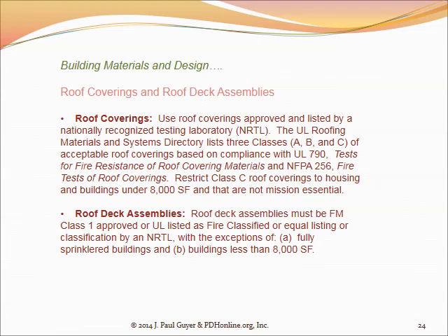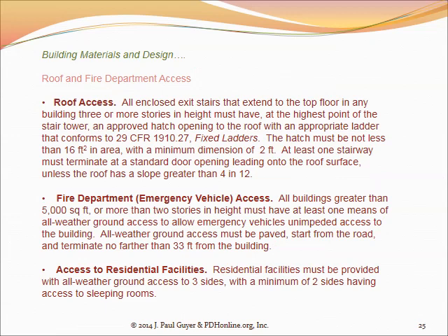Okay, another concept that is important as far as the roof is concerned, and really for the whole building, is accessibility for firefighters. In the typical fire situation, assuming it's a building that does have an automatic fire sprinkler system, there are two ways to put the fire out. One is with the automatic fire sprinkler system, and the other is the firefighters with their hoses.